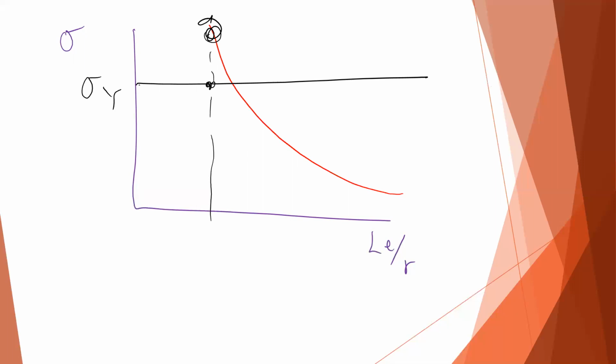What were you saying just now? What I'm saying is that we can calculate the critical buckling load or the critical buckling stress, and that'll give us the red line. But that's only meaningful if instability is going to happen before compressive yielding. If instead your material is going to yield and fail in compression, then that needs to be your design value.